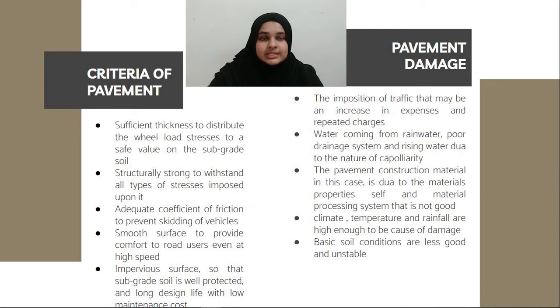So now I'm going to talk about the causes of pavement damage. So firstly is the imposition of traffic, which may be an increase in load and repeated charges. Secondly is water coming from rainwater or a poor drainage system and rising water due to the nature of capillarity. And the third one is the pavement construction material.